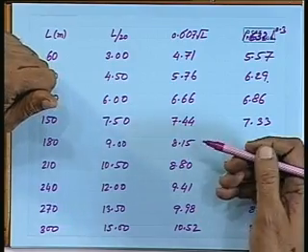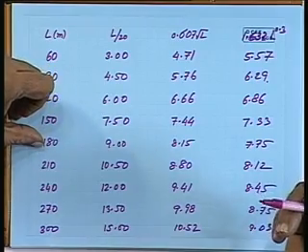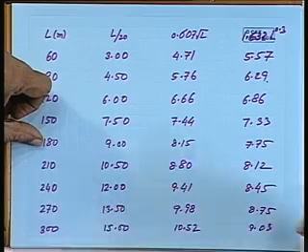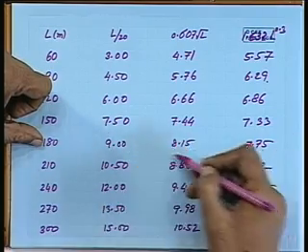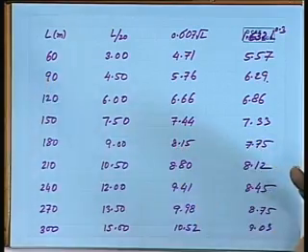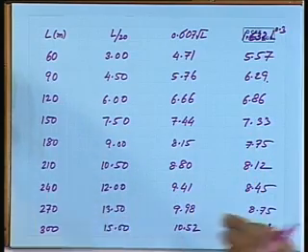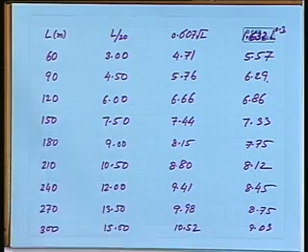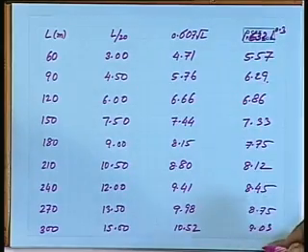But if the ship's length is more than 130 or 140, usually after that period the ship's length was about 180 to 190 meters or 200 meters, then one need not consider 9 or 10 meters height of wave, rather 8.15 or 8.5 meter wave height is more than sufficient. And even some ships were built, like Global Tikku etc., of a very ULCC or VLCC, much larger length. What is the point considering 15 meter wave height for that type of ship? So obviously, this formula holds good there.